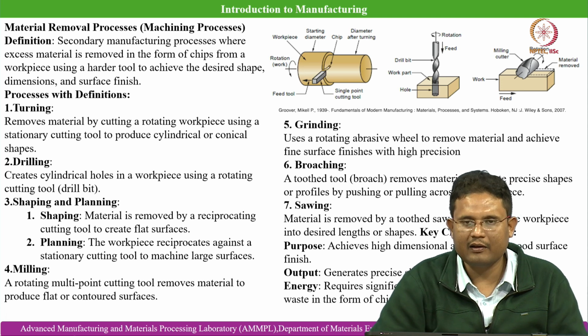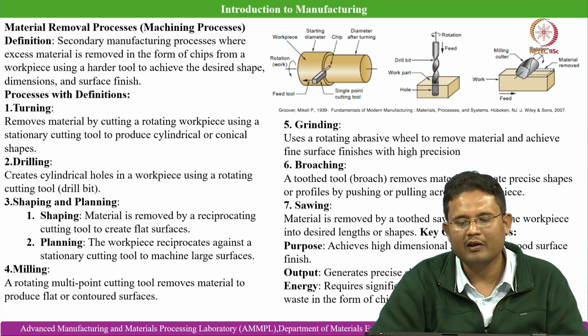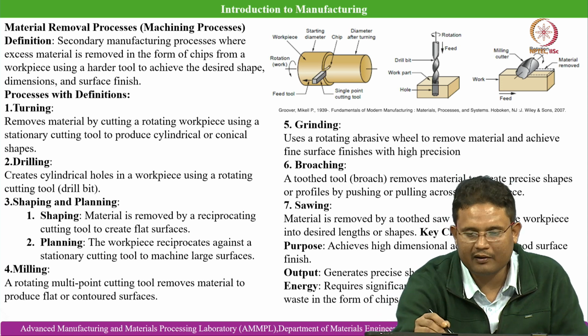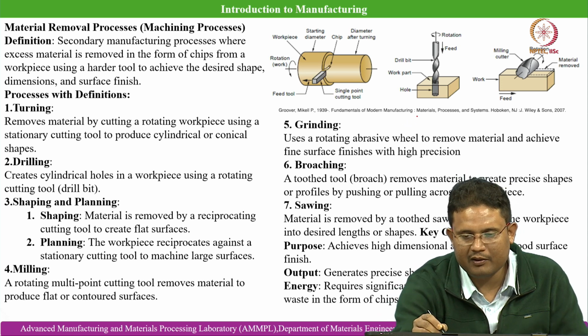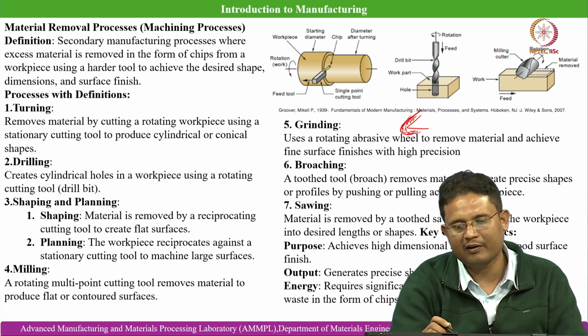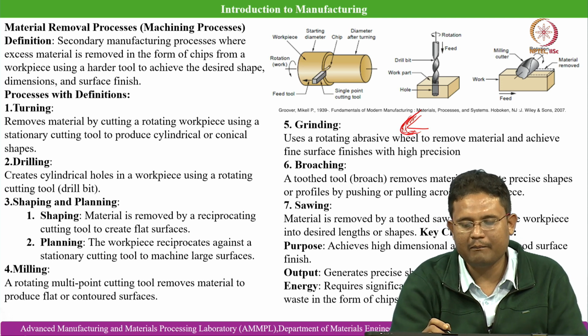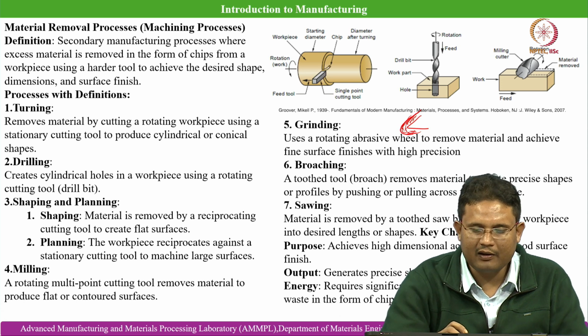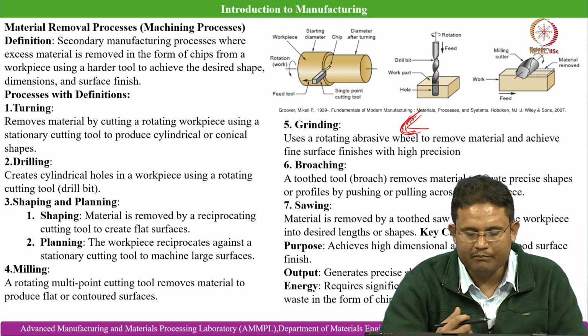So, in case of ductile materials, we often come across built up edge formation. When the chip is formed and the tool acts, the chip gets soldered over the tool, which makes the tool front blunt and also causes the built up edge formation. It is a phenomenon we often see in ductile metals, and it also impacts negatively, as it hampers the surface finish of the machined part.